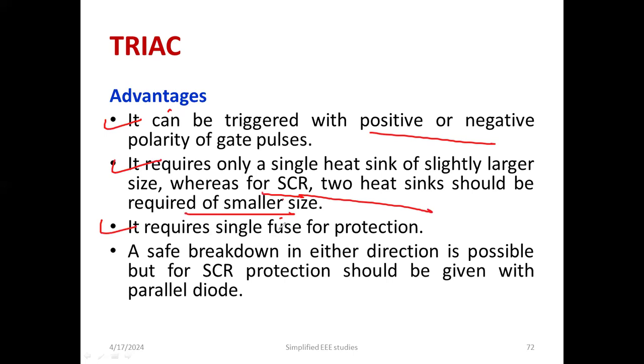It requires a single fuse for protection, unlike separate SCR fusing. A safe breakdown in either direction is possible, but SCR protection should be given with a parallel diode. So these are the major peculiarities and advantages of TRIAC.